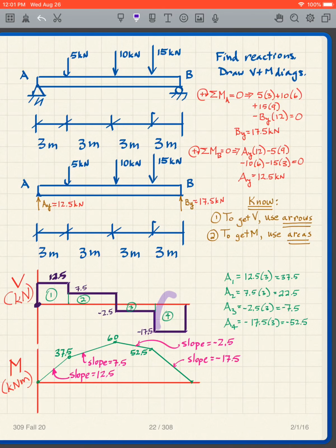And I know that it's in this region of the beam, so it's over in here. So if this beam were going to fail in shear, then it's going to occur in this portion of the beam. Why? Because under this loading condition, that region has the greatest shear, assuming the beam is basically homogeneous throughout. In other words, it's the same beam everywhere. So it takes us only a second to recognize that.